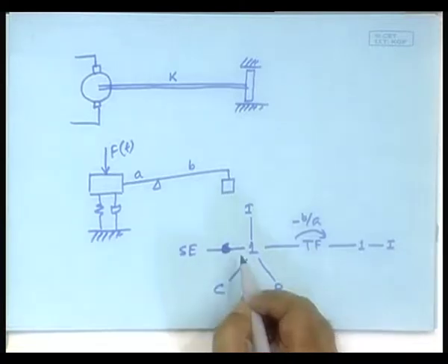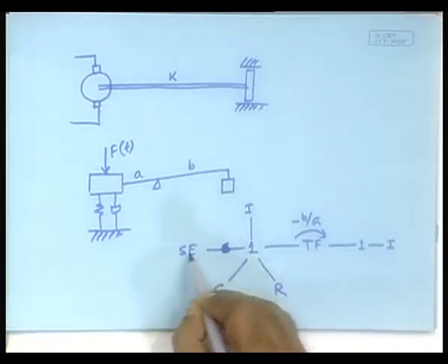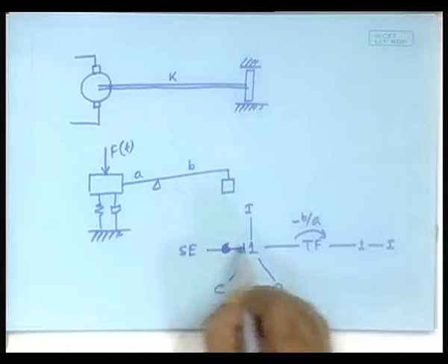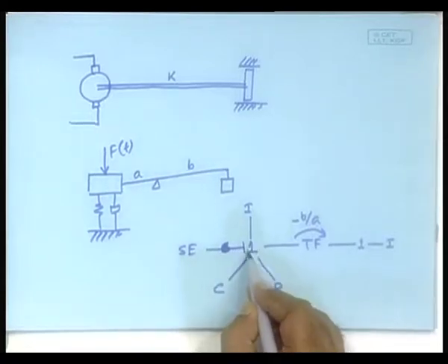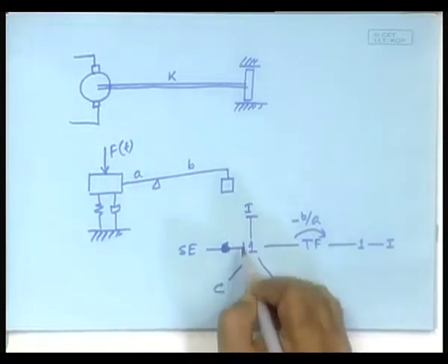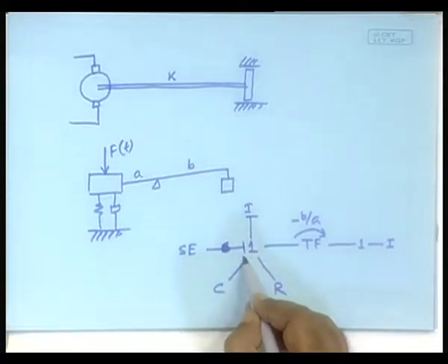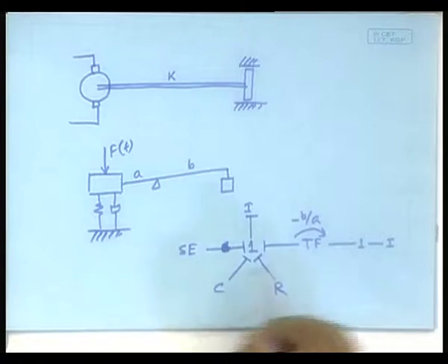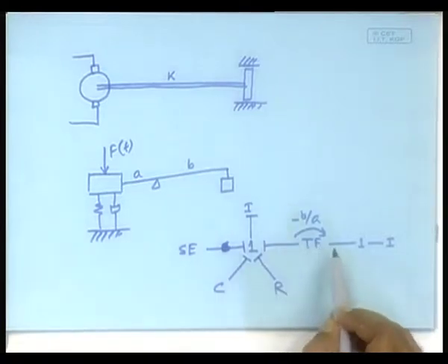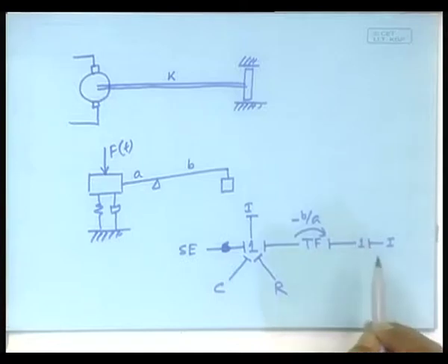In that case you would notice, let us just do this once again to refresh our memory how the differential causality comes. Suppose we start from here, the C element receives flow and gives effort. Now, this one junction will be integrally causal. So, this brings in the flow information, the other ones must distribute the flow information. A transformer has received the flow information, therefore, it must give out. One junction has received the flow information, therefore, it must give out. Now, here we find that this is not properly causal, it is differentially causal, because it is receiving the flow information. So, that was the point.